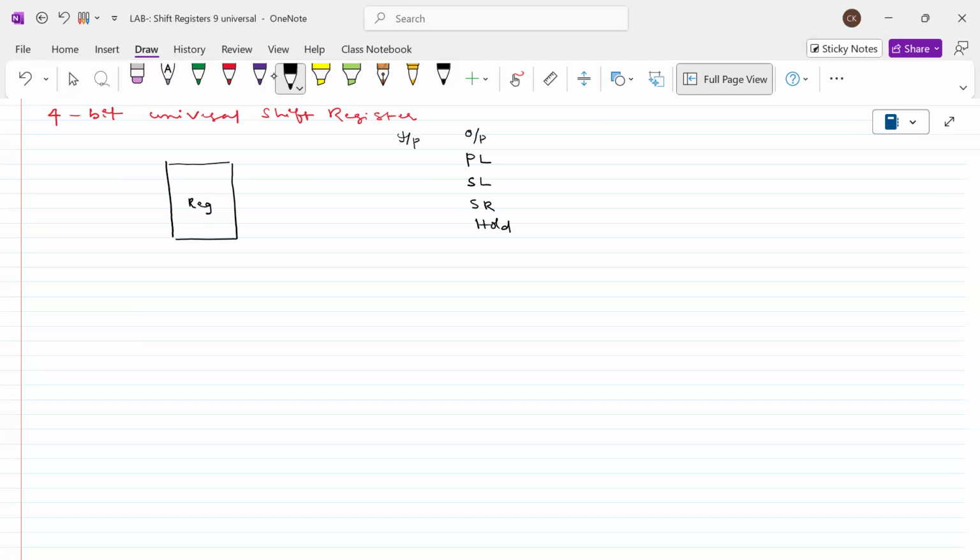Okay, that means this is an output and input is actually, most important one is selection line. How many selection bits do I have to consider? 2 bits, because 4 possibilities. 0 0 means this will be selected as an output. 0 1 stands for this one. 1 0 stands for this. 1 1 stands for this kind of operation, right? That means there is an information here that is called 4-bit data in signal. Then you will get 4-bit output Q.